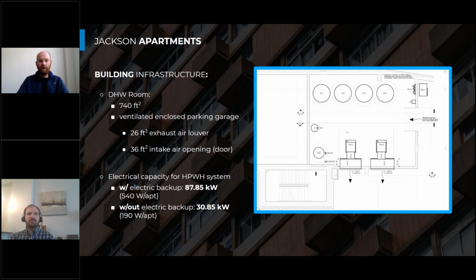Yeah, so when the heat pumps are on, they're going to pull in air and discharge it out. If you connect the discharge to the exterior of the room, then we're pushing air out, which creates a slight negative pressure in the room, which will pull air into the room. And that's our makeup air opening. So we're not ducting or forcing the air in, we're just letting it passively come into the room and making the heat pumps force that air out of the room.